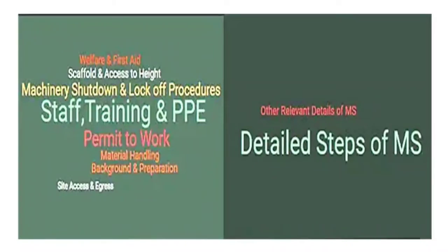Right? Now, let us go to the next section, which is recommended but not mandatory. What are such documents which are recommended but not mandatory? One is earlier submittals. Sometimes what happens, the drawing revises, your method statement will revise or scope will revise or ITP may revise. So, if you are submitting the revised ITP, say R1 or R2, you need not submit an entire MS or method statement for just an ITP. So, it is always recommended but not mandatory.